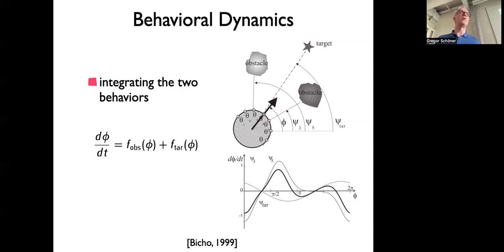If you have servo motors, it's reasonably good. And then from that new position that you estimated, you compute the orientation to the target that you initially gave. That is something that will drift over time as you make errors, so it only works for a short range, but that's a typical approach. And that is actually something that humans do. I'll talk about that in navigation. You can actually close your eyes and then make a few steps and approximately know where you are.